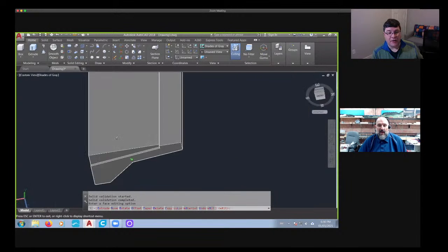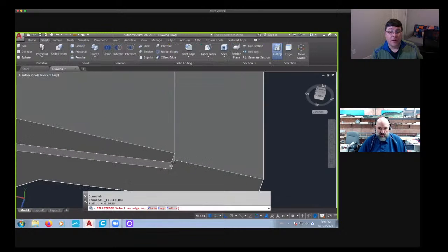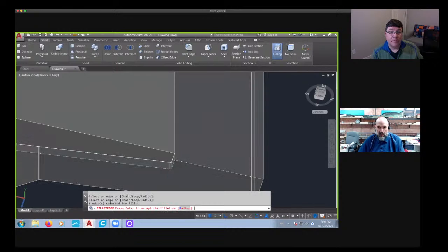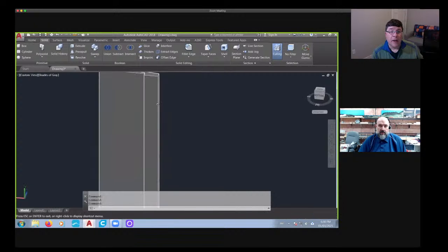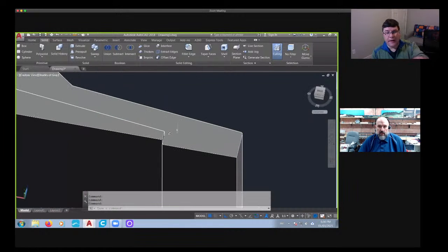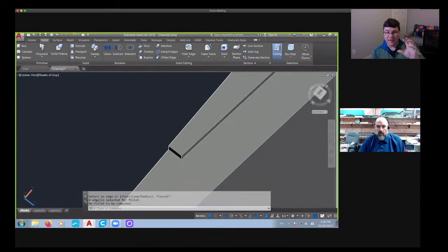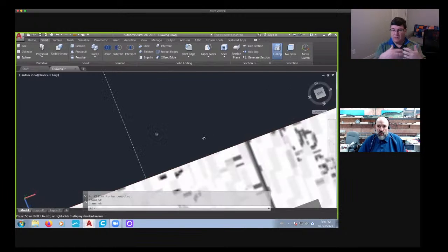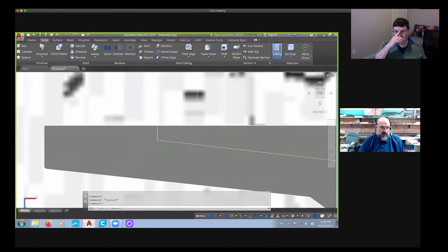And then what I'm going to do is fillet these edges again. Right? And then the other side here. Now, would you make this side where the bump out is, would you not just make the fillet? Would you actually make it slightly smaller? Sure, let's do that, just because when you print it, you want to be able to stack them like the real thing. Right.